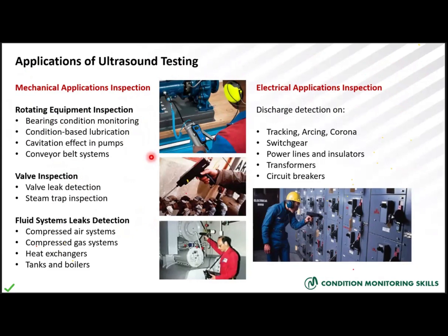For any valve inspection, valve leak detection, and steam trap inspection, we could use ultrasound. Fluid systems like compressed air systems or compressed gas systems, heat exchangers, tanks and boilers, faults in all of these could be detected using the ultrasound technique.